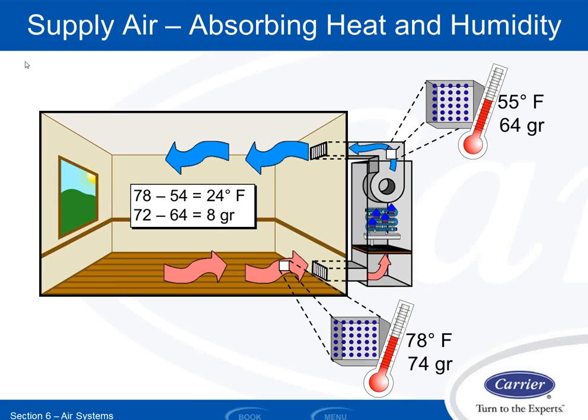Some of those heat sources, like infiltration and people, also have a latent component to them, right? So people are sweating and giving off moisture, and infiltration is leaking in potentially moist air from outside. So there's a sensible and latent factor to both of those. Other sources like lights, solar, and transmission are just straight sensible, right?